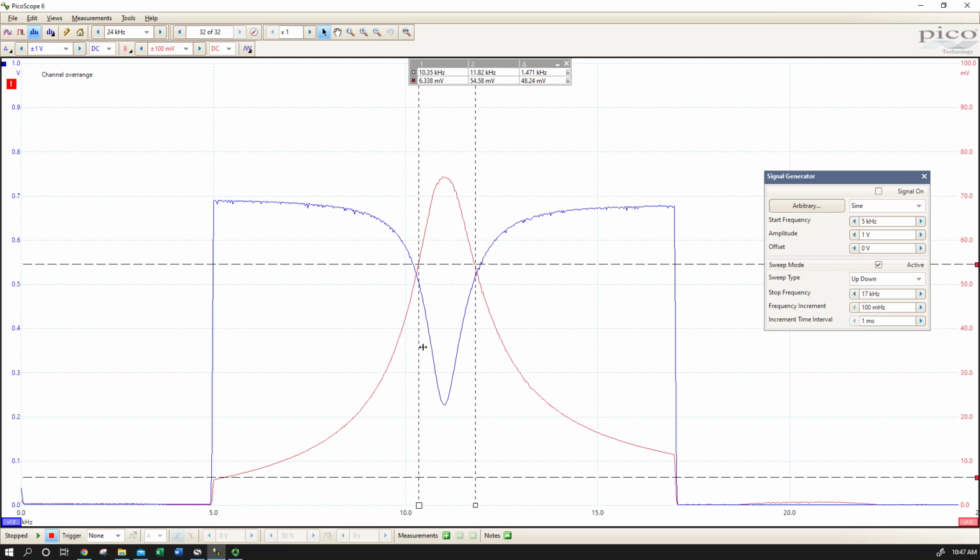And in both cases, what we're looking at are the frequencies that span the point at which we would have half the power being dissipated, either whole circuit or over the resistor. So that gives us an idea of the frequency span over which we're getting this big change in impedance in different parts of the circuit. And this lets us select where we're going to send signals in our subsequent circuits depending on their frequency. And of course, for those of you who might go on to RF studies, that's fundamental in transmitter and receiver technology, as well as any kind of signal processing.